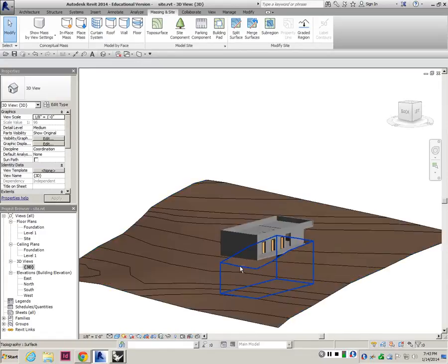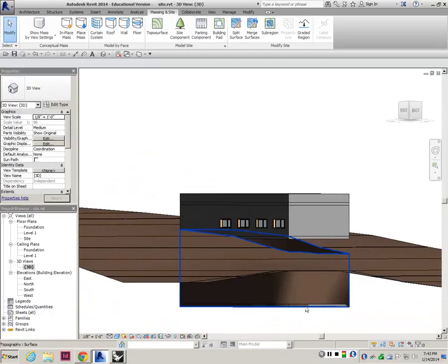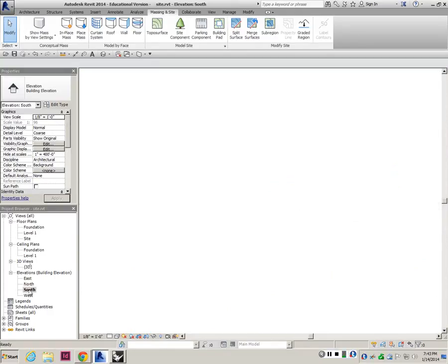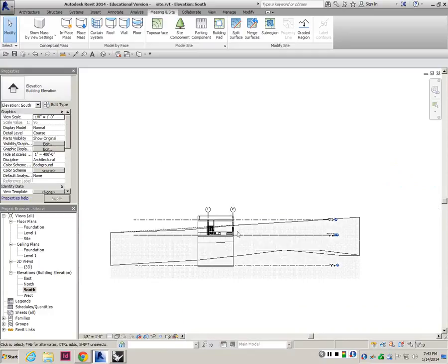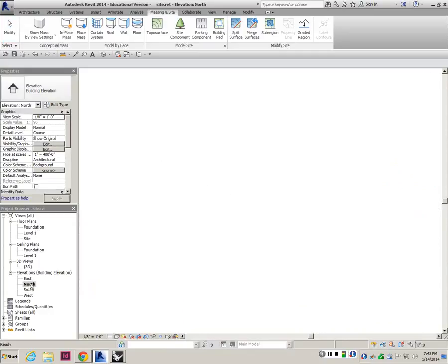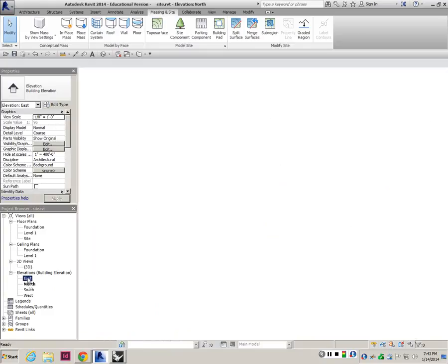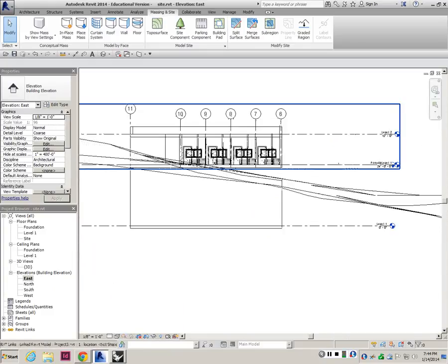Okay? Now if you look at this, the building pad is created at this level by default. It's normally created at the sea level. So if you go to the elevation, it's actually a bit harder to see here, but rather than hidden view, you could do wireframe view. This would actually show you all the detail or all the elevation of it. Okay. So I'm trying to find the side view, which is this one. Let's go back to the wireframe view.